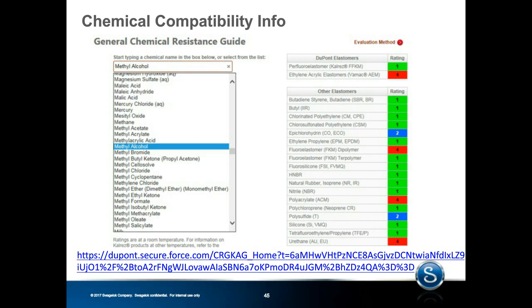So my recommendation to you is if you're using chemical resistance guides such as this, please make sure that it does break down the difference between the FKM types. If it doesn't, you don't know which type they used in the testing to develop the data for their guide, and unfortunately, I don't see how that data is useful to you. So be very careful to make sure that the guide gives you enough information that you could know specifically which elastomer material is being used.